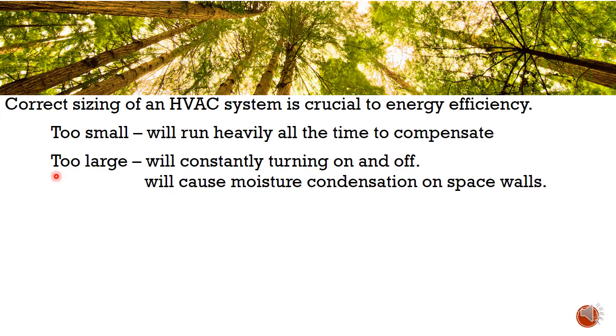And if the system is too large, that causes the load to be achieved within a short period, then it will constantly turn on and off, because after the set temperature is already achieved, then it will turn off. It's too fast, and after a while it will turn on, and after it just started, then it turns off again because the set temperature is already achieved. So that cycle will happen continuously.